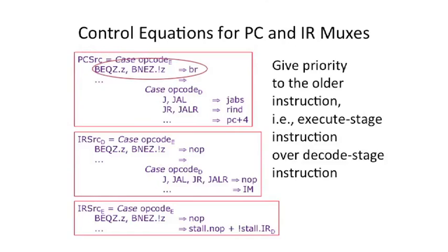And then we have these signals coming out of the execute stage, which is strictly farther down the pipe, and this needs to take precedence over that. If you have a branch which is directly followed by a jump, the jump's going to be sitting there trying to swing the control on the PC select mux, or the next program counter mux. You can't let that happen. You have to let the branch that's actually executing take precedence. That's really what we wanted to get across from this. Similarly here, the branch takes precedence over the jump and link for the other control signals.